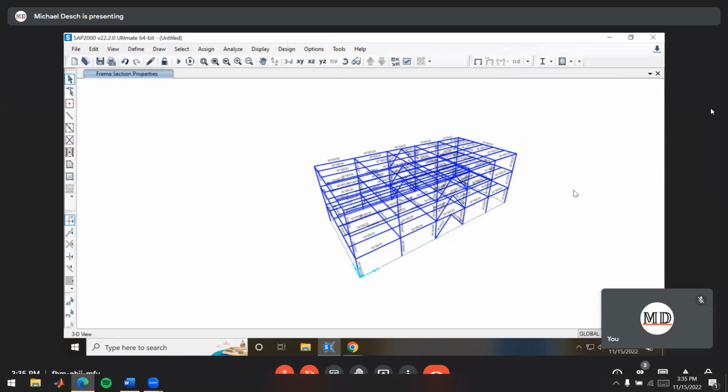Yes. So, are the columns selected automatically from the model because you defined them in AutoCAD? So in AutoCAD, when I was drawing this geometry, I drew a line for each element in the model, and I assigned each of them to a layer based off of what cross-section I knew it would be. So for all the columns, I said that would be part of the W18 by 97 layer, basically.